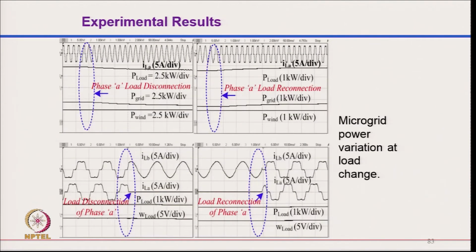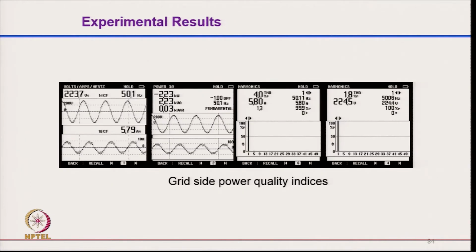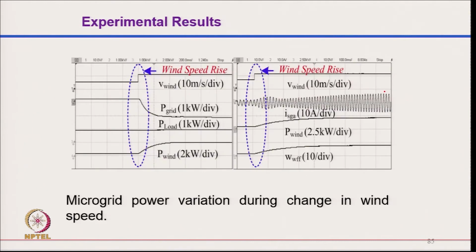It is able to improve the power quality. When you have a varying load, when you have a load change, the reference load current for the intermediate signal changes; when you apply the load it increases, and accordingly the reference grid currents change. You can clearly see the THD of the grid current is 4%, where the voltage THD is only 1.8%.